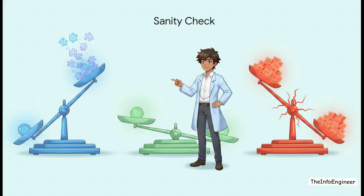If your degrees of freedom calculation does not equal exactly 0, the system is unsolvable. If it's greater than 0, you're missing information. Less than 0, your data is overspecified and might contradict itself. So if DOF is not 0, stop calculating immediately. I mean it, put the pencil down. You will save yourself hours of wasted effort. And honestly, this is exactly what separates process engineering professionals from students.